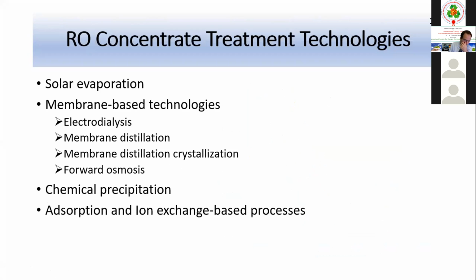So there are different technologies for treating RO concentrate. My research has just started in this area, and I am working on lithium and rubidium recovery right now using the ion exchange method. But in any resource recovery method, the first thing is that we should identify the extractable resources which have some economic value, then showcase the technology and assess them critically, and finally decide on the technologies to be used.